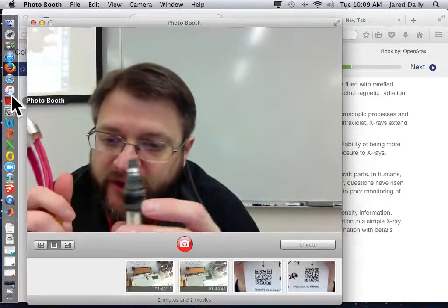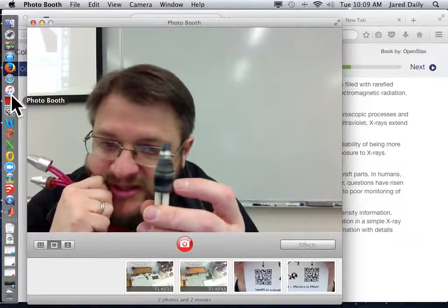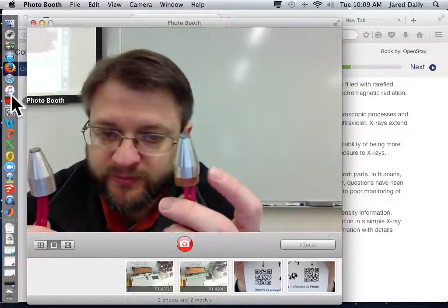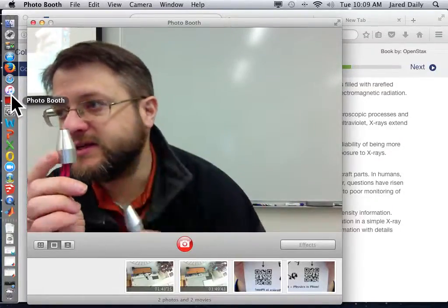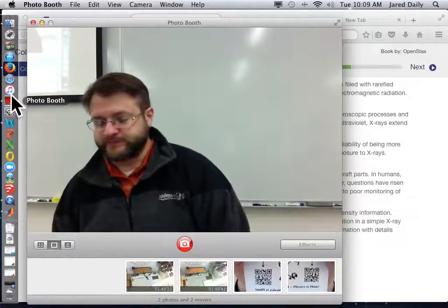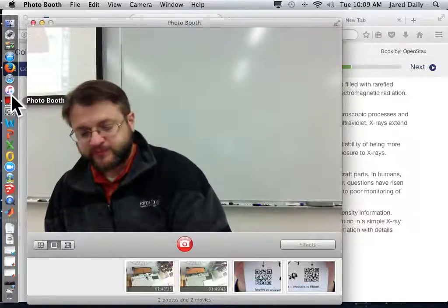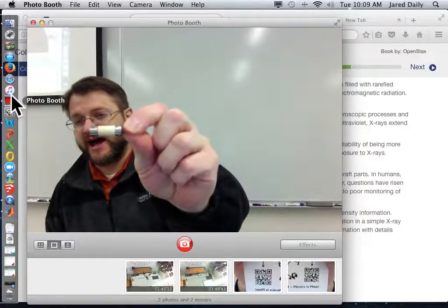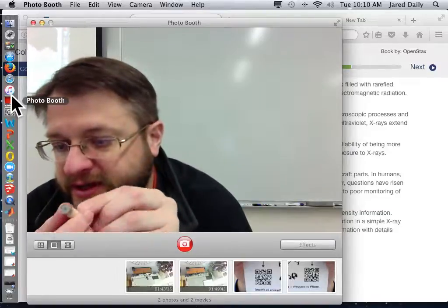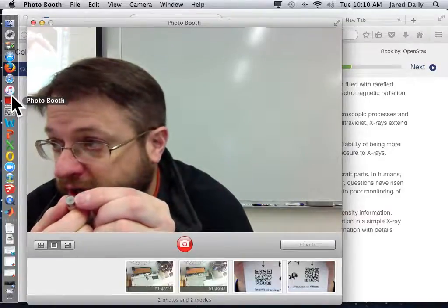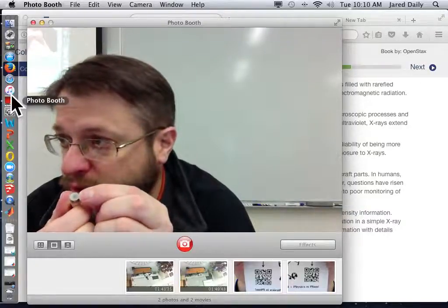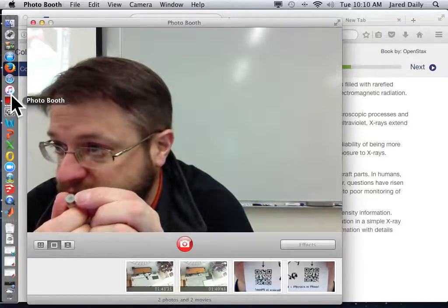And then at the other end of this thing, where you can't see it because it's covered in this epoxy, can't see it in these ones either, but at the other end of this is essentially a little light bulb. This is what it looks like inside if you took all the epoxy off. This end is where you have what is called the target. This is what is called a window target. So the window is made of beryllium, but it's coated in silver, and the silver is the target.